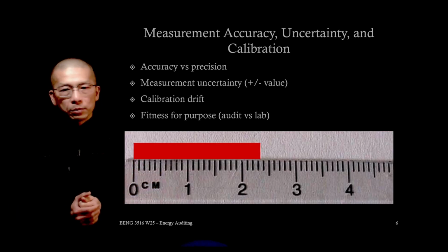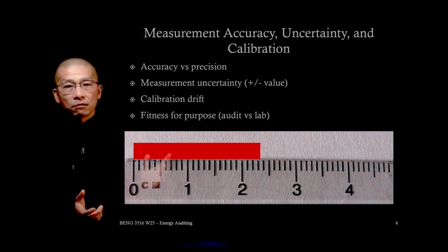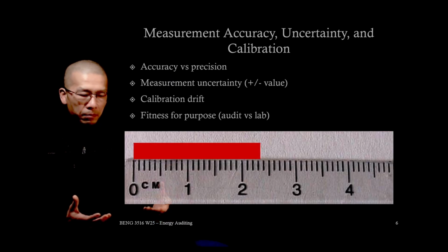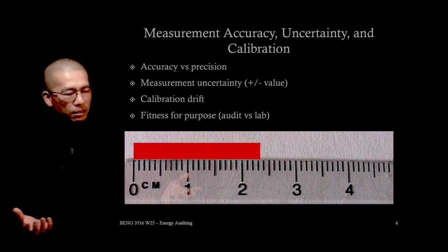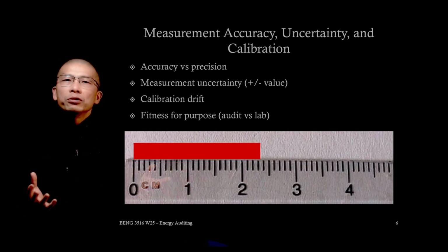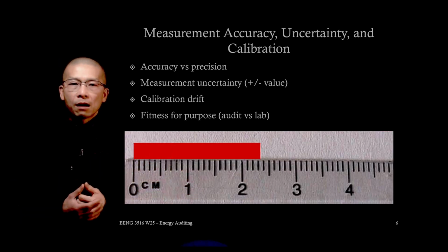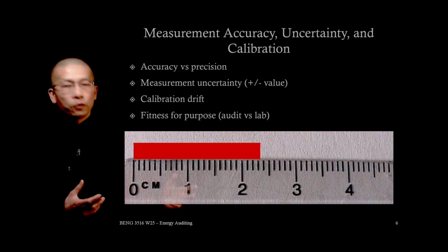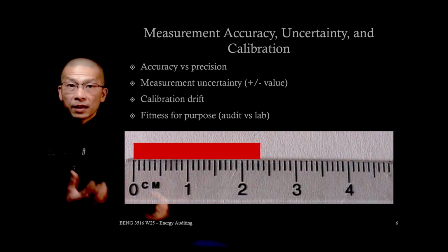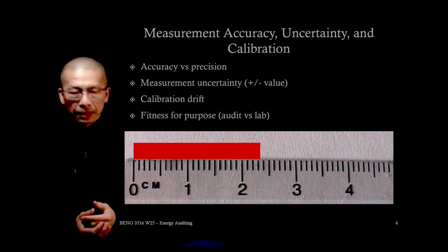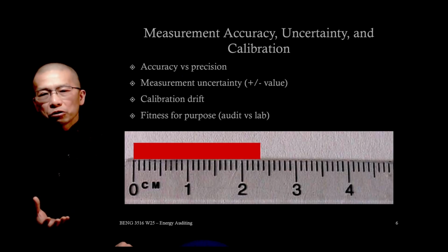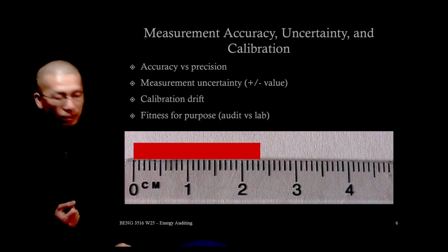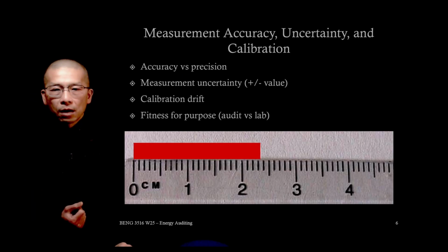Finally, not all measurement requires sensors and data loggers. Sometimes maybe just manual measurement, right? Like insulation thickness, duct dimensions, damper positions are often faster, cheaper, and sufficiently accurate for audit purpose if they are measured manually. Okay. The key question is not is it digital, but if it's accurate enough to support our audit or what we are making.